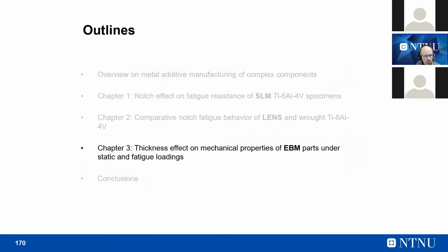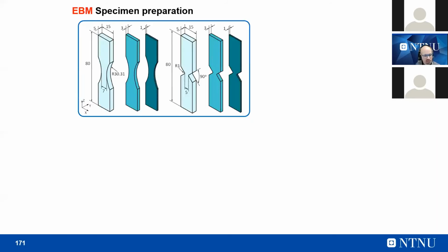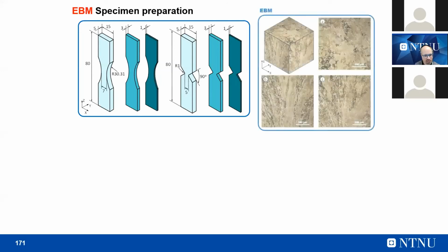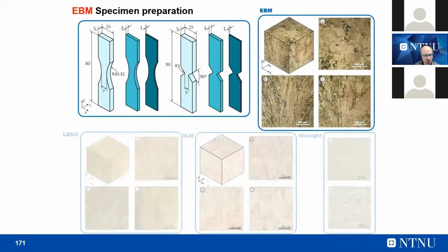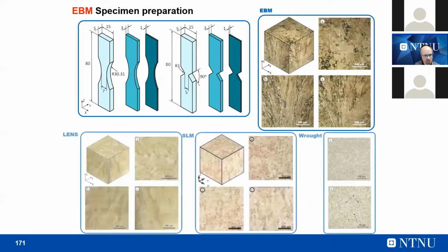After that, we also considered additively manufactured material under static and fatigue loadings. Here we studied an interesting effect, the thickness or scale effect, which for me is always a key point that we have to consider in research, especially when we deal with fatigue issues. Due to the cost and limitations in printing, we have considered only a limited number of cases up to now, but these cases were able to show us how strong this effect is in fatigue design, and how it affects the final fatigue behavior.